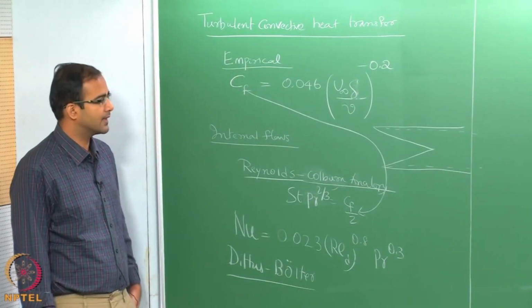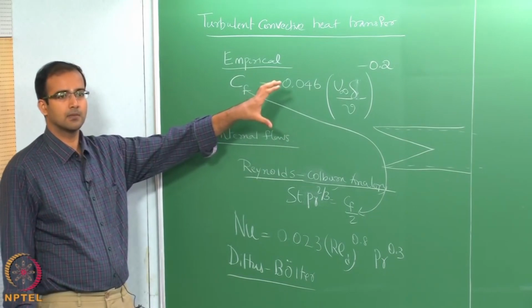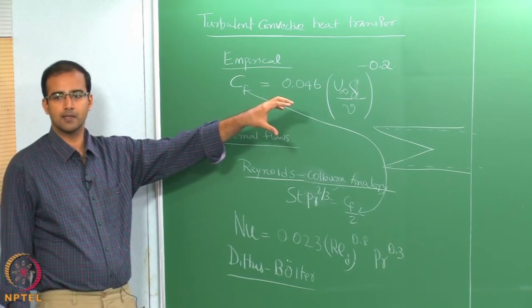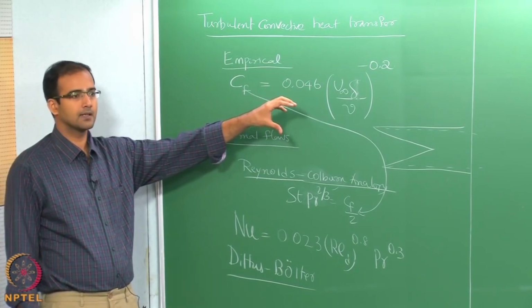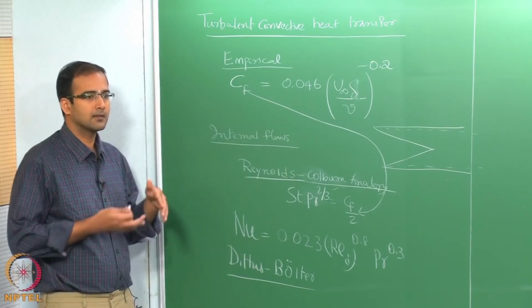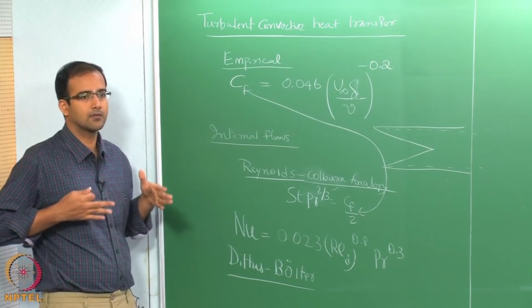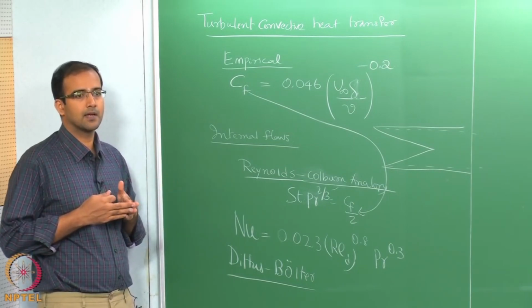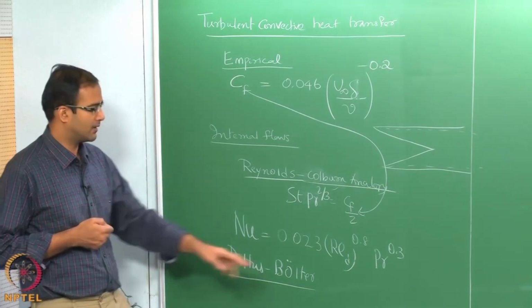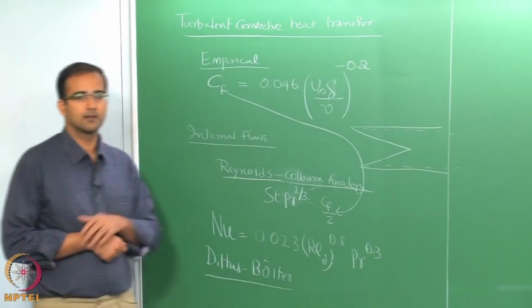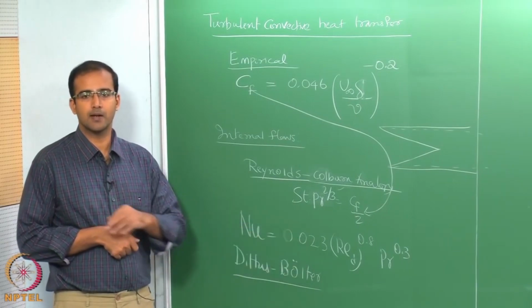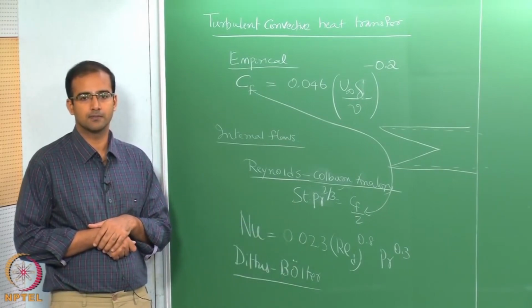Okay. So, therefore, there is an influence of Reynolds number now, because Reynolds number controls the amount of this viscous sublayer thickness, okay, which in turn affects your Nusselt number. So, although your turbulent boundary layers are fully merged, your viscous sublayer is still remaining, which is now governed by the value of Reynolds number, and therefore, that comes into the expression. And so is the case. Now, since this is a heat transfer case, Prandtl number will also be important.